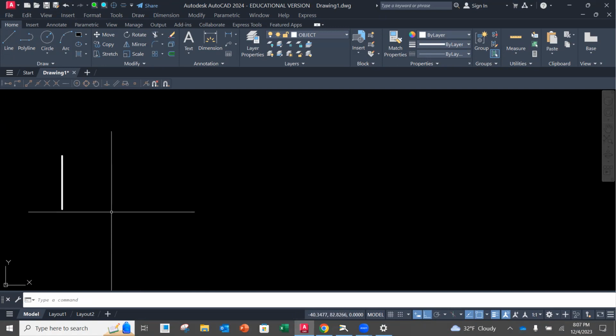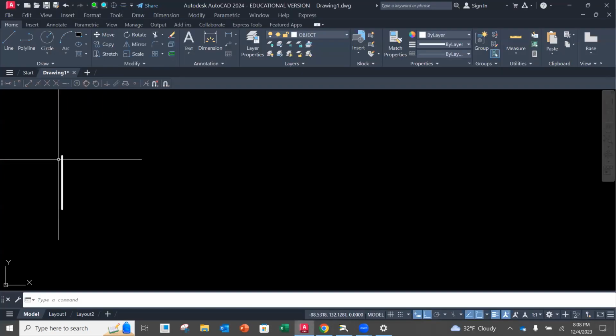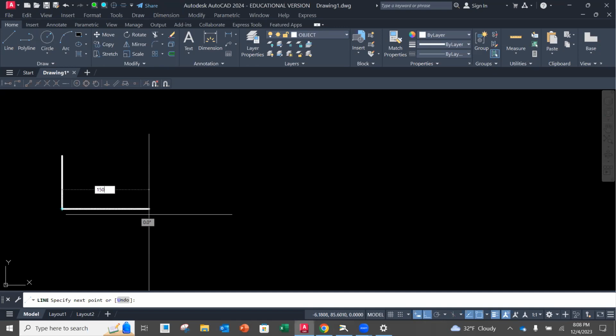Now, a good place to start, as we look at the 50 here, as I said earlier, if we look underneath, you'll notice that you have 50 on that axis. And if you go 1, 2, 3, about 3 times that length is going to be a good guidance or a good place to start for the length of your x-axis. So that's what I'm going to do. Since we had 50 along the y, I'm going to draw a line then, starting here horizontally, going 150 millimeters long. Okay. All right.